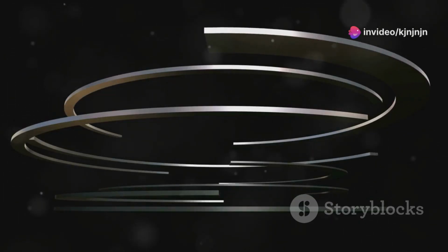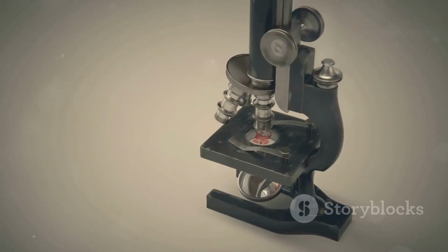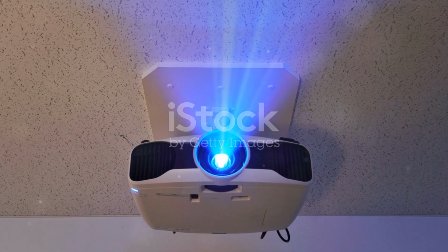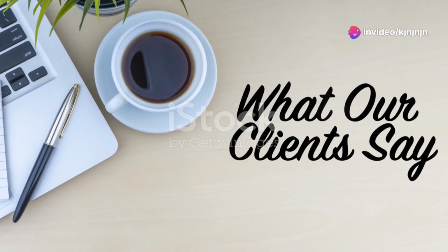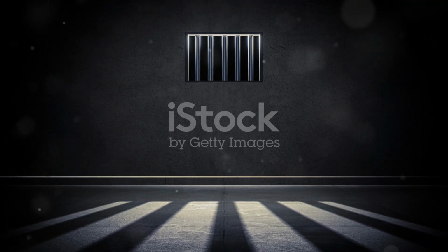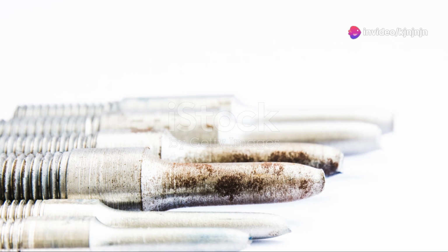Stressed models placed in a polariscope, an instrument used for photoelastic analysis, reveal intricate interference patterns. The polariscope consists of a light source, two polarizers, and the stressed model. The light source emits polarized light, which passes through the first polarizer. The polarized light then interacts with the stressed model, causing birefringence. The second polarizer analyzes the resulting light, revealing the interference pattern. By rotating the polarizers, different aspects of the stress distribution can be visualized.